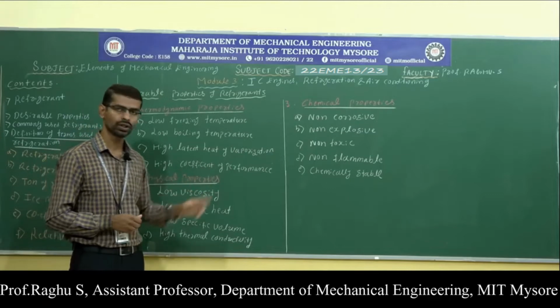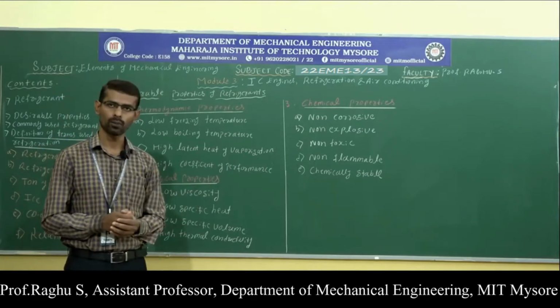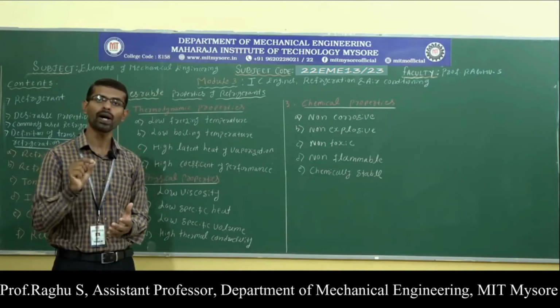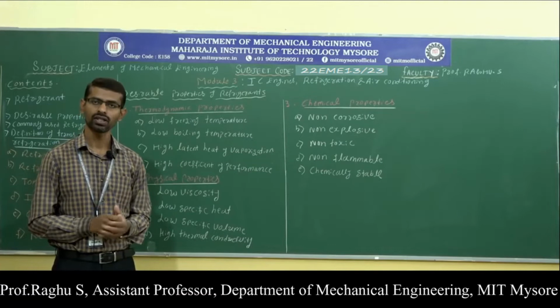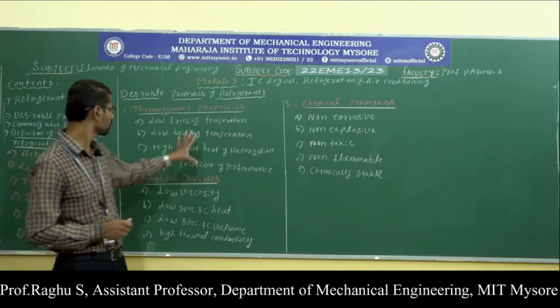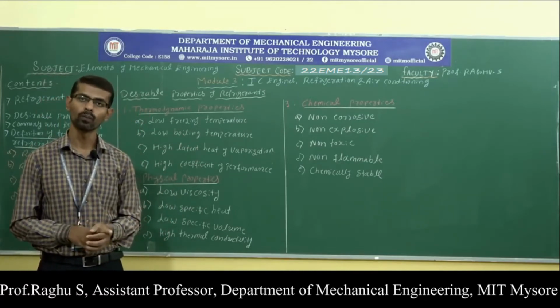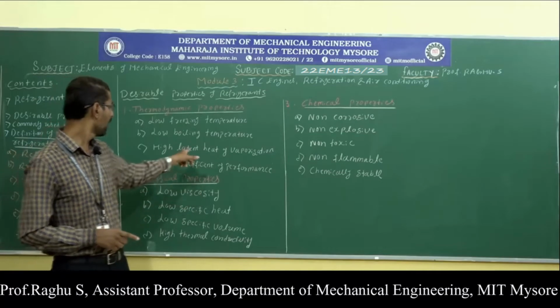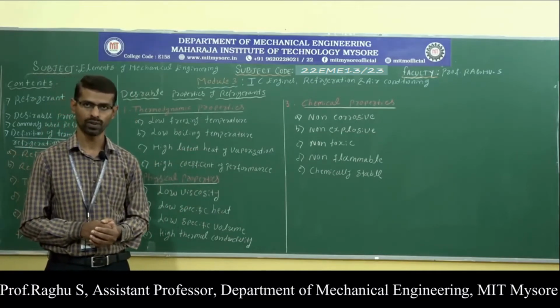Then high coefficient of performance. A good refrigerant should have high coefficient of performance, so that the energy spent in refrigeration will be very less. So these are some thermodynamic properties: low freezing temperature, low boiling temperature, high latent heat of vaporization and high coefficient of performance.